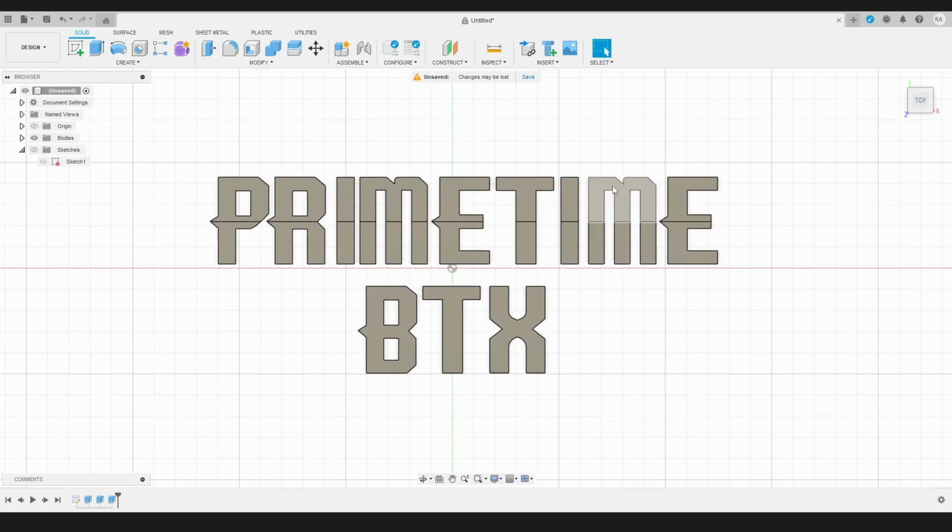Now, if I were to try to 3D print these letters as they're extruded currently, I could do that. The only problem is when I go to get it off the print bed, they're going to be loose, and I won't have any reference to guide me as far as the spacing in between the letters and the design. And you could also run into additional problems where if you don't wait for it to cool down enough or it's not thick enough, when you go to pry these off your print bed, they may warp and bend, which we really don't want either.